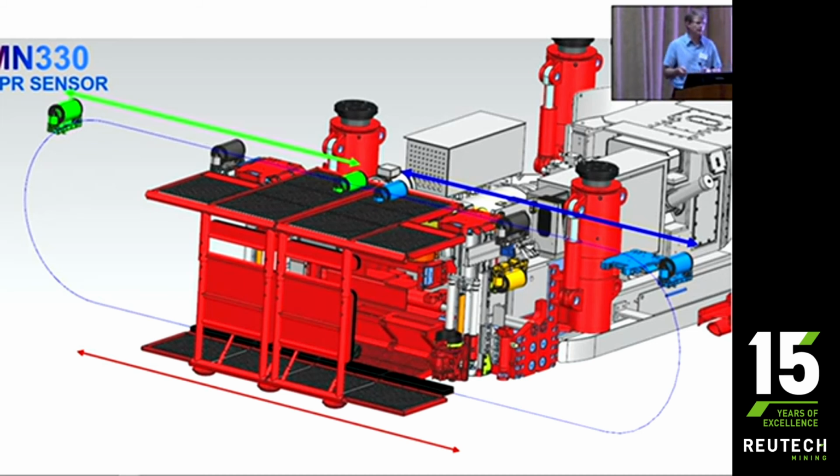Now, cutting is fantastic. It's God-gifted for geotechs, because nothing falls out. But because nothing falls out, you can't map anything. You only see a line on that hanging wall. That's all you see. You see one line, and if you don't see it in the sidewalls, you've got no idea where that thing is dipping. You only literally see that joint line on the surface.